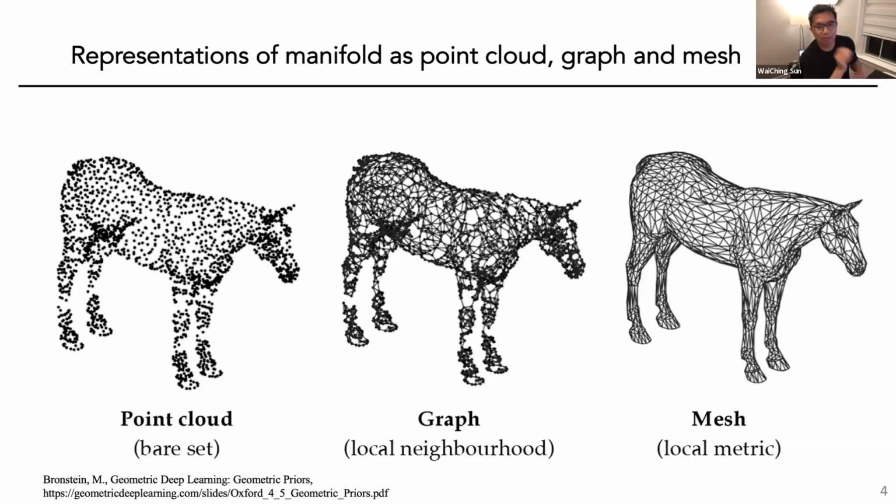But notice that there is a slight difference between representing the geometry, where we need to put the points, and what we actually need to have sufficient resolution for the boundary value problem. For example, if I have a heat source or I load this horse structure, I may have a stress concentration where geometrically there is nothing interesting, but I would need a very fine mesh.